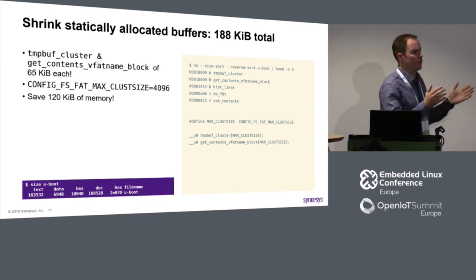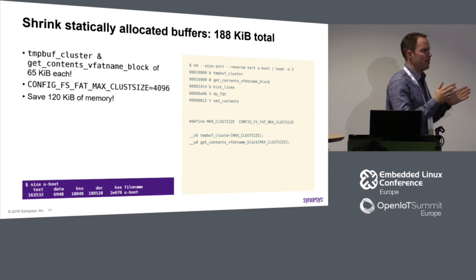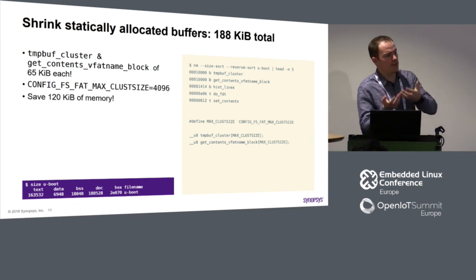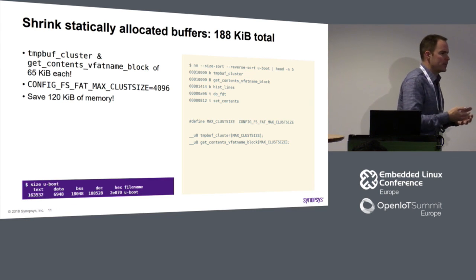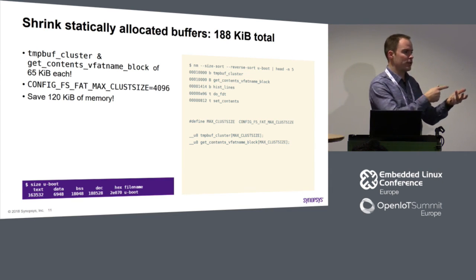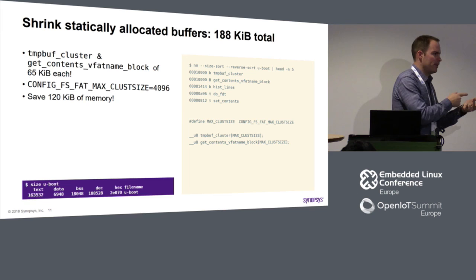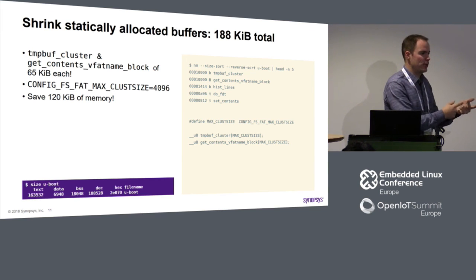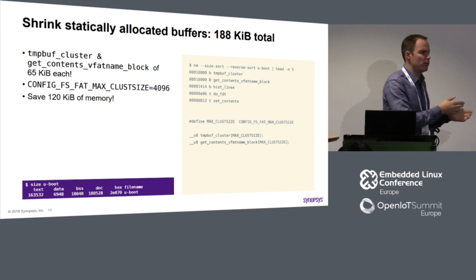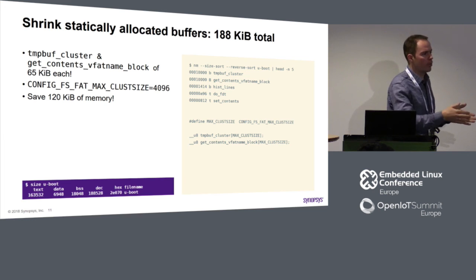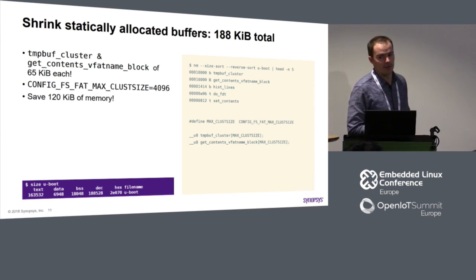Then you start execution from there, and with SPL you initialize your DDR, and then you may load the real full-scale U-boot from an SD card into that DDR, because you already have a driver for SD cards and a file system, which you are not able to have in a pre-bootloader because you only had a couple of lines of code there. So you see, on each stage we are becoming more and more powerful, and in the end we may do whatever we want. That's the beauty.